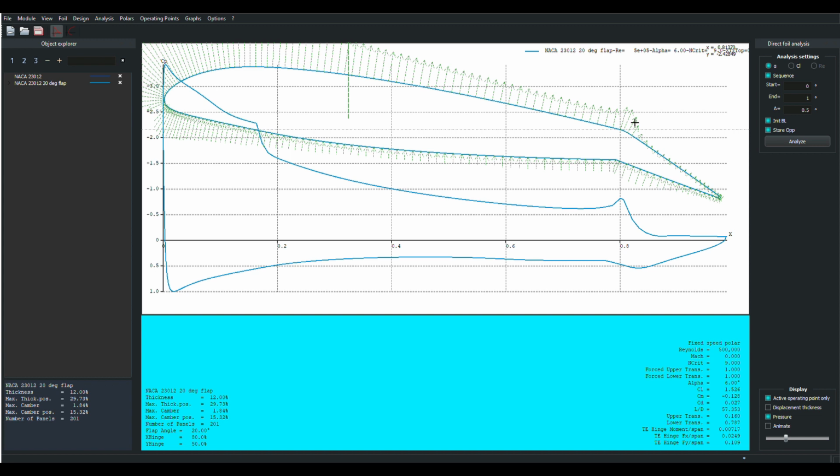You know, as an aerodynamicist, it's not every day you see flow going one direction, then just take a hard left or a hard right, 90 degrees, and go the other way. But this would cause that. And when you're standing there trying to visualize the flow, there's many things you visualize, but you don't visualize this hump in the pressure distribution, this drastic increase in adverse pressure gradient. And as I talked through this whole thing with Peter, Bob was talking about this pressure differential stuff, pressure gradient.